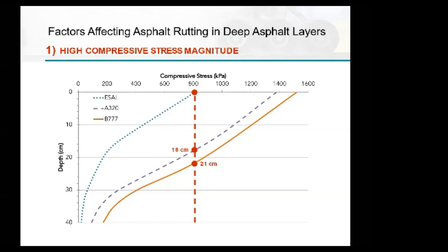So whatever I'm doing for a highway pavement in Superpave for grade bumping, I'm worried about 800 kPa, so I'm bumping up the grade. Well, that 800 kPa is still there in the airfield pavement, but it's not at the top. It's much deeper. So something needs to be done for the deeper layers. Can they take that high stress? I typically don't optimize my binder layer to be top notch, but yet I'm seeing stresses are still high.